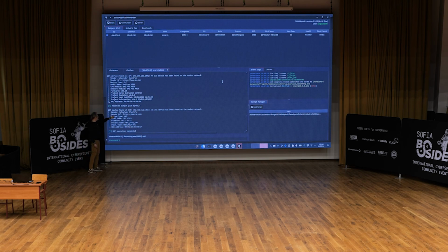Then we discover another device, an HMI, human machine interface, by Schneider, called XBT GT43, this version and this MAC address. Interesting. These are important pieces of information that we got from the PLC. For example, the firmware version. I can Google Modicon M580 version 3.10. I also suggest 3.20 because I worked on these vulnerabilities. They declared to fix this vulnerability with 3.2, but it's not covered. Okay. Oops. No, it's not true. You can use it also with version 3.20, and you can find some vulnerabilities that can be addressed with this kind of version of